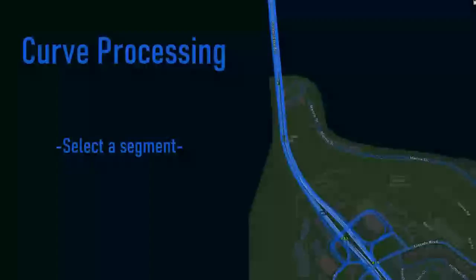One of the things we do when we drive the network is we don't typically do 2 passes in one day at the same time. We do them on separate days, so that if there is satellite positioning that might have had an issue one day, we can get stronger GPS data on the next day. But the inclinometer is going the whole time.